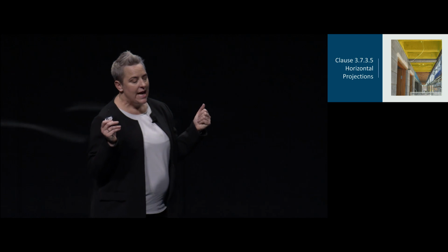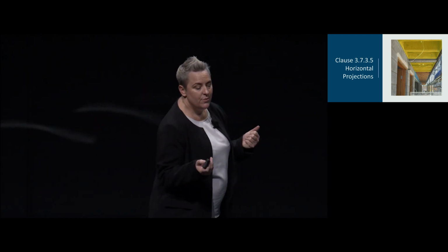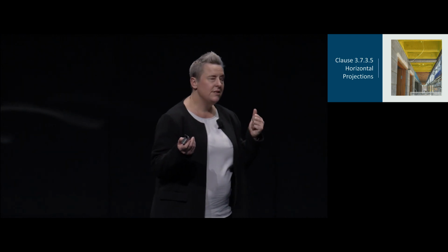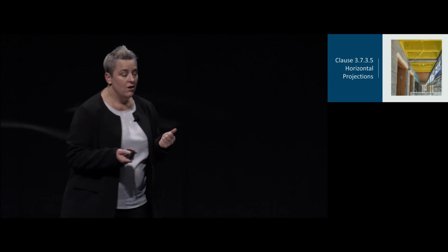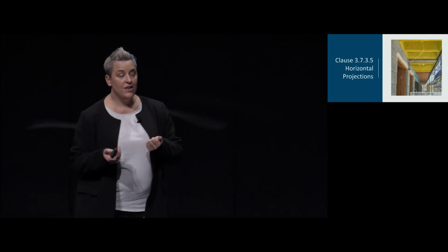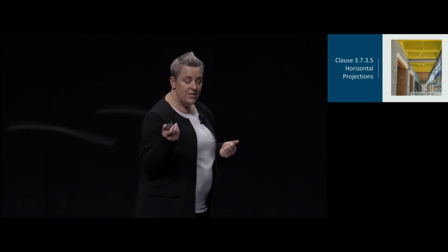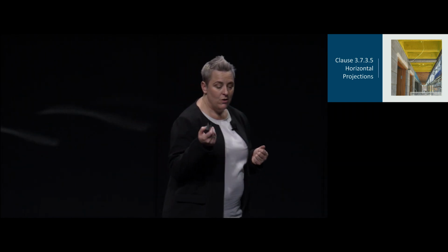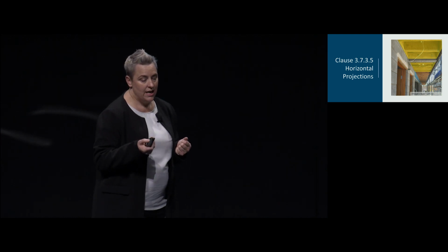And once again, the ceiling with a resistance of an incipient spread of 60 minutes, or an FRL of 30, 30, 30, or your fire protective covering on the underside of the floor. So once again, your fire protective covering can be your 13mm fire protective grade plasterboard or your 12mm cement sheeting.